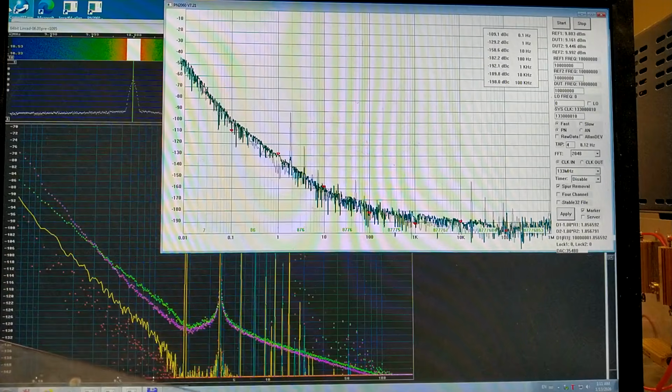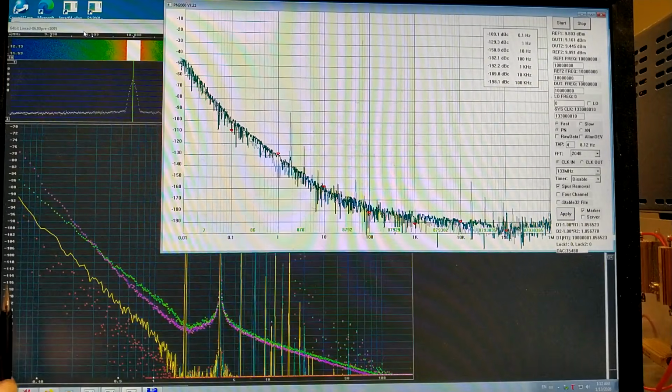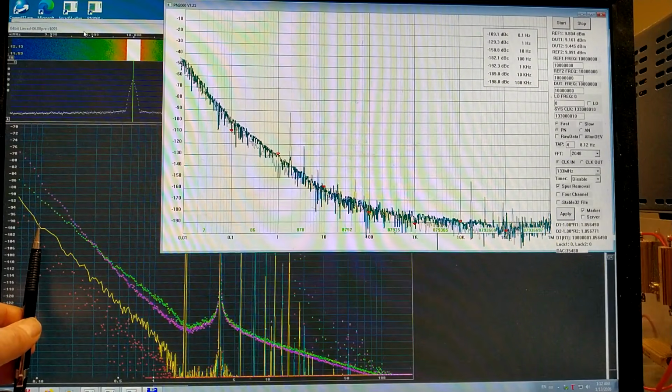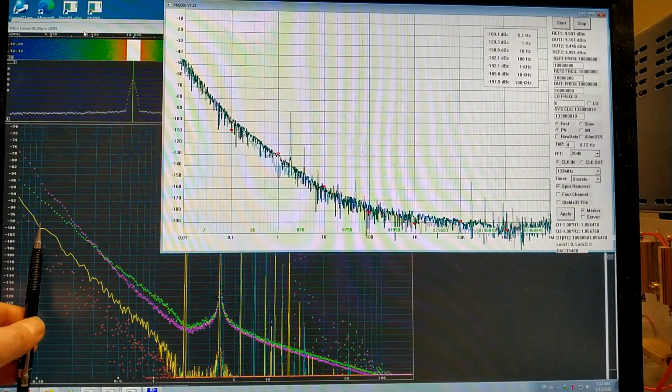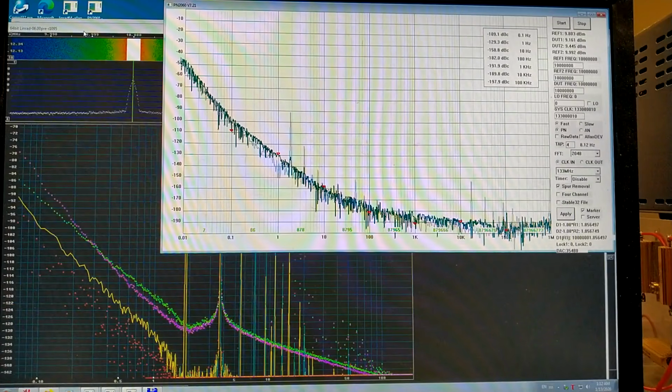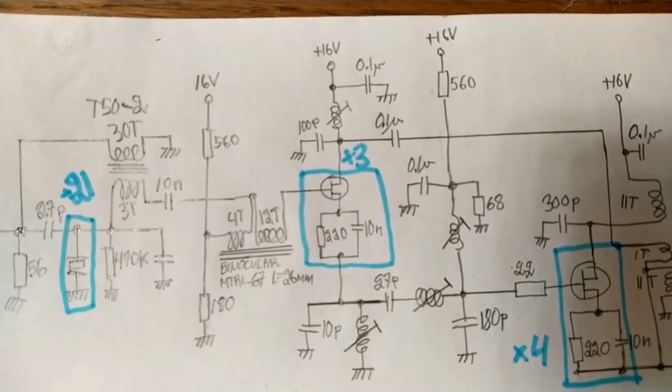If I look in Linrad, at 1 hertz it's minus 131. At 0.1 hertz it says minus 99. Actually minus 100, but that is statistics, I think. So this is fine, but the very long time constant when switching the unit on is inconvenient, so I will not use this. I found that the source follower at the input is slightly saturated.